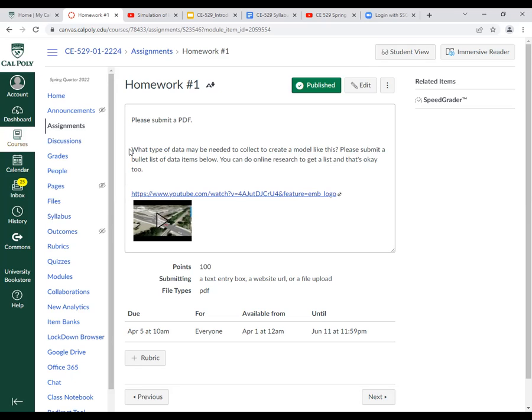It's not real obvious, because when you're building the model, if you're modeling just one location, one intersection, then maybe having traffic counts is all you need. Because in a traffic intersection, if you have the turning movement counts, that's all you need. If you know how many people are going through, right and left in each approach, then you're good. But in a model like the one that you saw, let's say you knew traffic counts at certain points on this Cal Poly map, right?